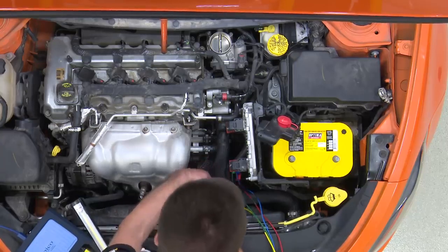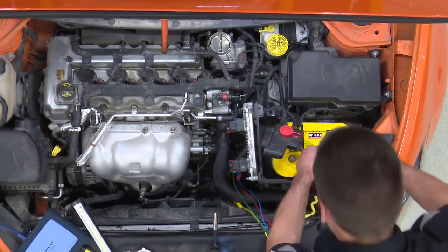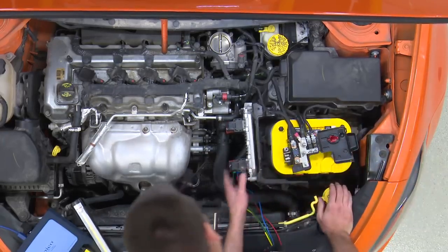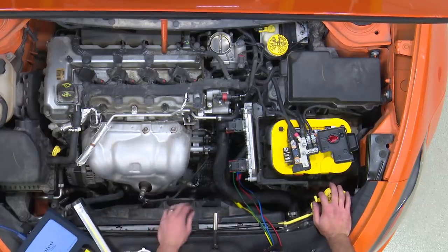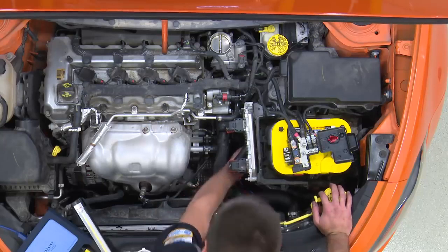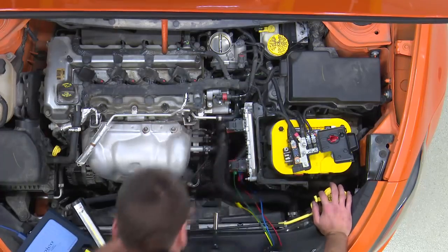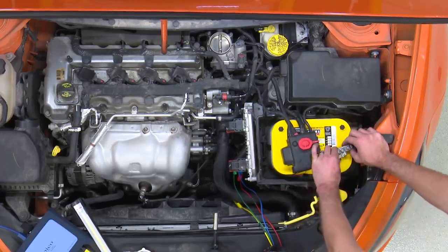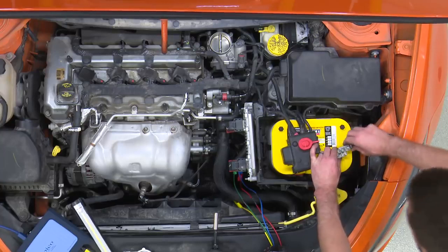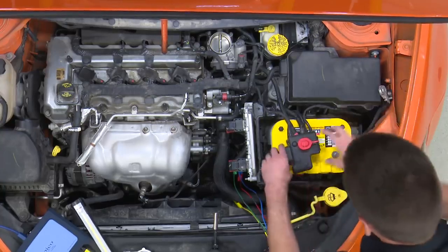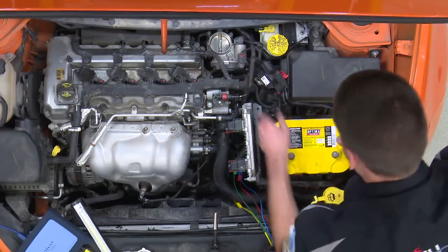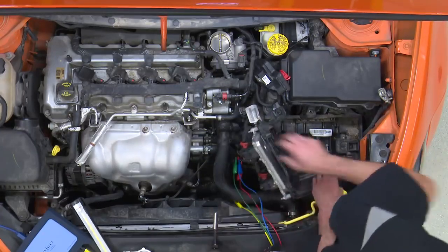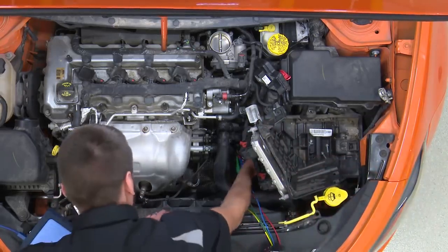So before you start this process, put the vehicle in neutral so you don't deal with what I'm dealing with right now. Alrighty, so we should be makeshift back together. Jim, can you go ahead and shift this thing into neutral for me? Alrighty, there we go. And just like I thought, our shift cable lines up with that hole in the switch. All right, our key off? Oh, that's right, can't key off. Kill the battery power, we'll leave it in neutral. Maybe slide this out of the way or not. Oh, that might work. We'll slide that out of the way. Here we go, a little time-saving tip.